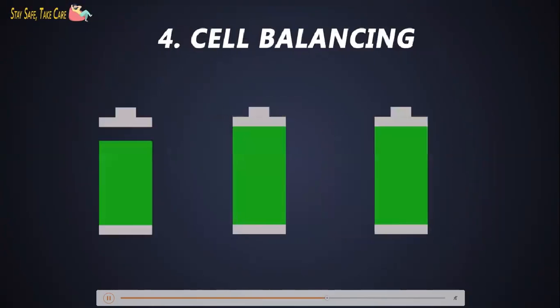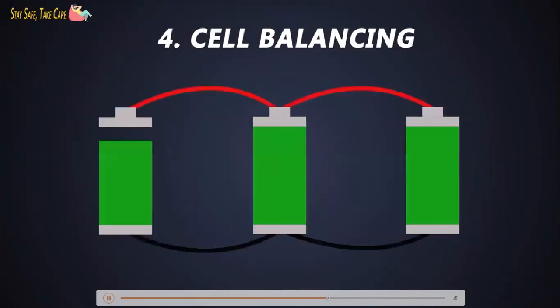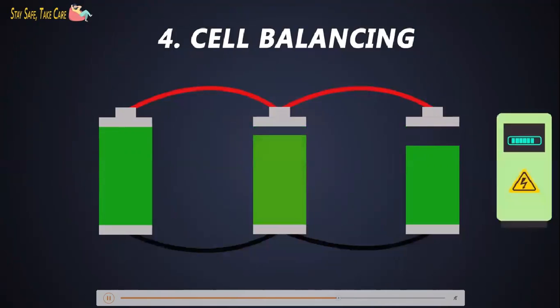Next comes the cell balancing. Cell balancing is a method to compensate the weaker cells by equalizing the charge on all the cells in the chain to extend the overall battery pack's life. In the whole battery pack, small differences between the cells are due to the tolerance of operating conditions, which gives rise to uncertainties during charging.